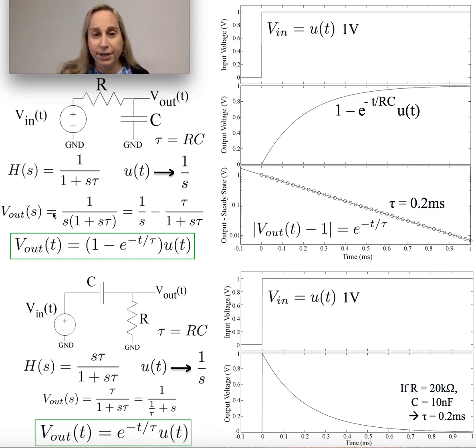In this particular case, it gets slightly more difficult, but not much. It's just a touch more algebra, where I need to take this and transform it to a 1 over s and a tau over 1 plus s tau, which basically gives me the exact same form I saw underneath here. And it turns out this would be a separation I would get. Again, you can create this and then solve for what the appropriate structure should look like. Not too difficult to do. It's an algebra problem probably many of you are familiar with. And so at that point, I get these two pieces.